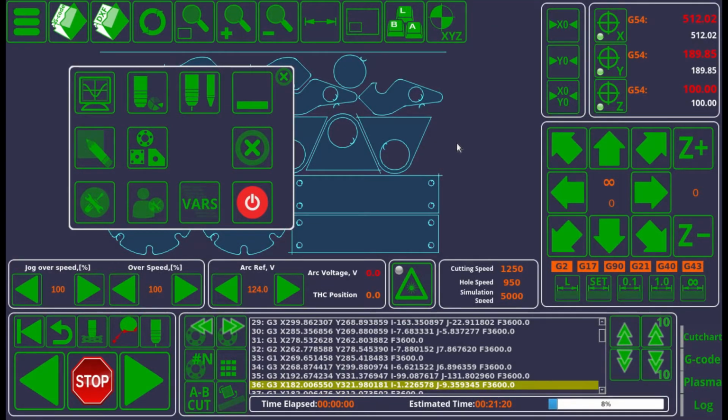And the issue here is twofold. Those signals can either be too narrow, so they're not wide enough, and if they're not wide enough, then they're effectively appearing and disappearing too quickly, so to speak, and the controller can't actually see them. Or they may be too wide, and in that situation the signals will overlap, so your pulses will conflict with one another, and you won't actually have meaningful signals sent to it. You will instead have a bunch of overlapping signals. And this necessary pulse width will be different depending on which motor type and motor brand you're using.